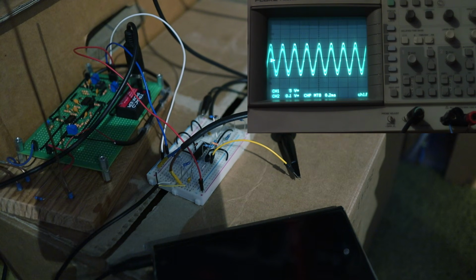Now, you do have to be careful when you're reducing the attack time, because it is also possible to make it too fast. And what happens if you make it too fast is that instead of responding to the amplitude of the signal as a whole, the circuit actually starts to respond to individual fluctuations in the signal. In other words, it starts just distorting the whole thing.